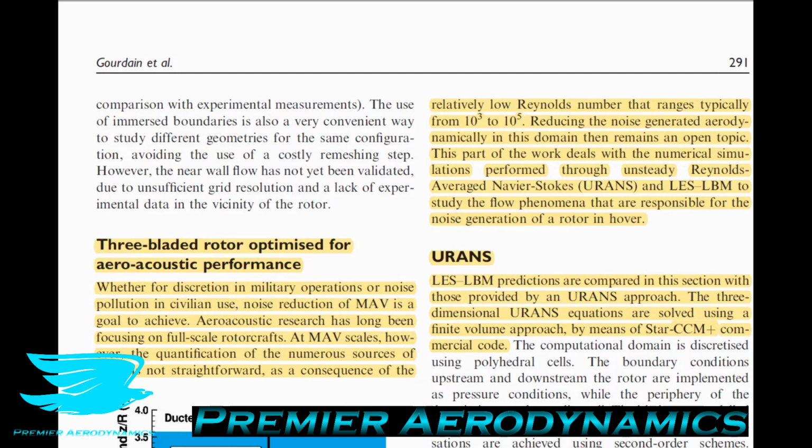This part of the work deals with the numerical simulations performed through unsteady Reynolds-averaged Navier-Stokes, or URANS, and the LES LBM, so large eddy simulation for the Lattice Boltzmann method CFD, to study the flow phenomena that are responsible for the noise generation of a rotor in hover.